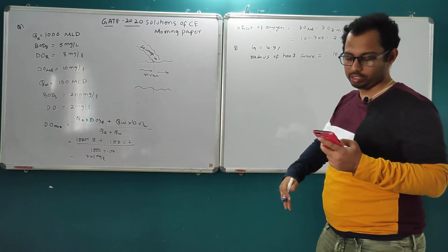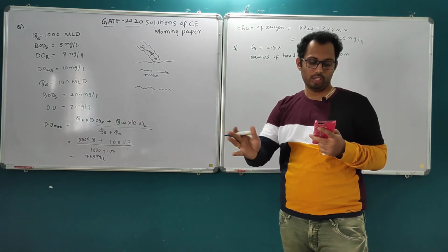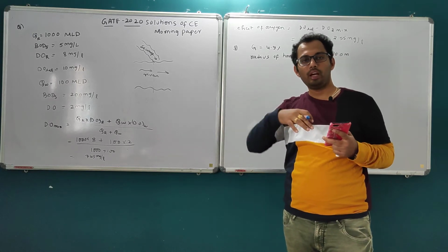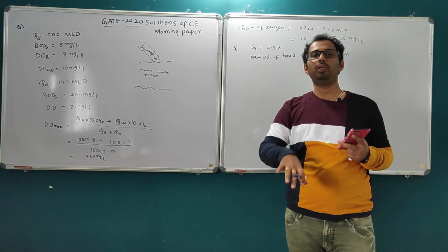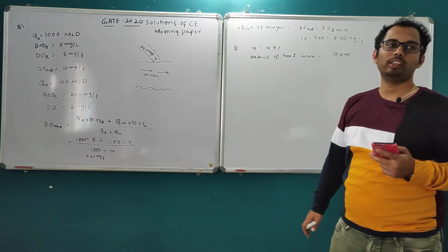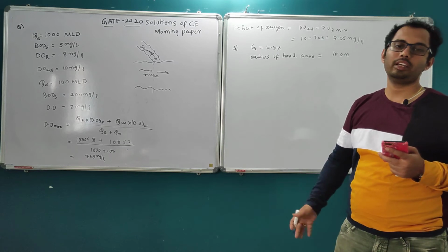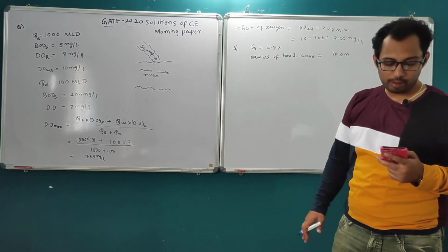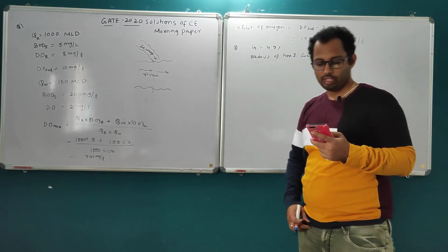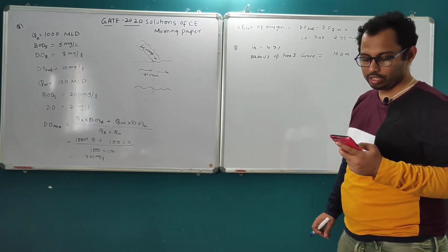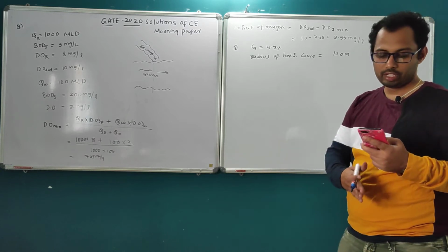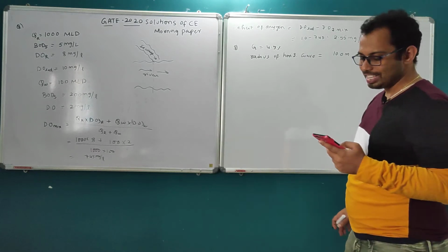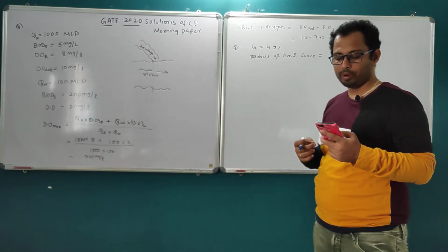Gradient needs to be eased because it is a horizontal curve. So because of this horizontal curve coming on the path, the gradient should be eased. Otherwise what happens? The vehicles may skid or topple in the horizontal curve. So that is why the grade compensation we need to give. Okay, so the question was gradient needs to be eased due to the combination of curved horizontal and vertical profiles. Okay, so as per IRC, everybody knows this.